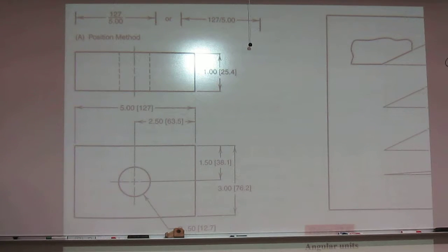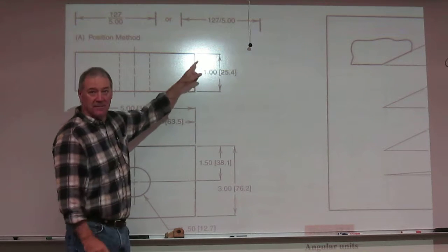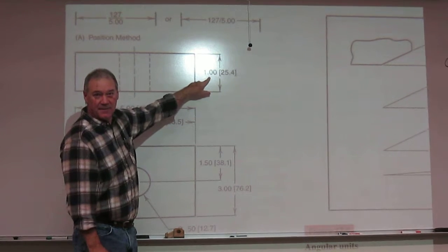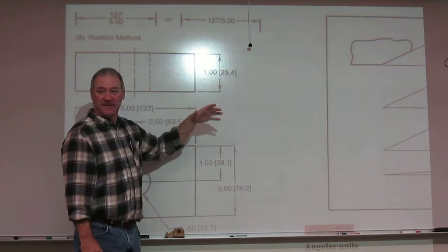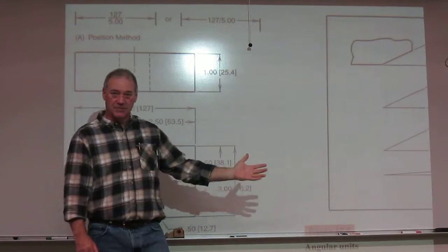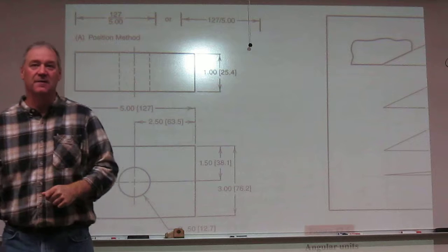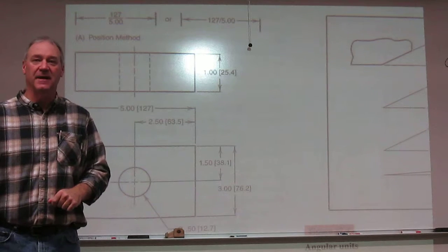So would you have to include anything in your notes for this? No. You do include the same tolerancing techniques and everything for your main unit of measure. So your main's outside. So if I'm doing English units, then I would still give them a tolerance in English. I'm not going to give them the metric tolerance. They would have to convert that tolerance.